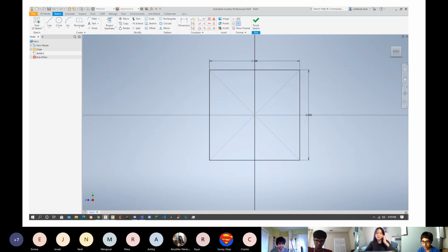Backwards compatibility is also why we want to have nice and neat orderly sketches, so that we can modify things after they're actually created, instead of having to create a new part every time you want to make a small basic change. Less is more with constraints. It's just easier to modify them. Just tiny things like that. Okay, yeah.